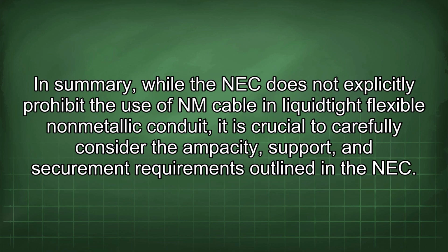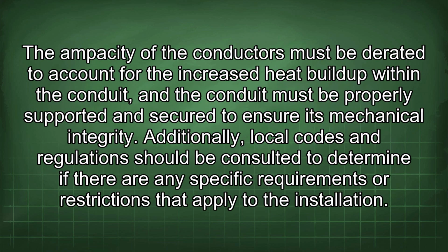In summary, while the NEC does not explicitly prohibit the use of an NM cable in liquidtight flexible nonmetallic conduit, it is crucial to carefully consider the ampacity, support, and securement requirements outlined in the NEC. The ampacity of the conductors must be derated to account for the increased heat buildup within the conduit, and the conduit must be properly supported and secured to ensure its mechanical integrity.